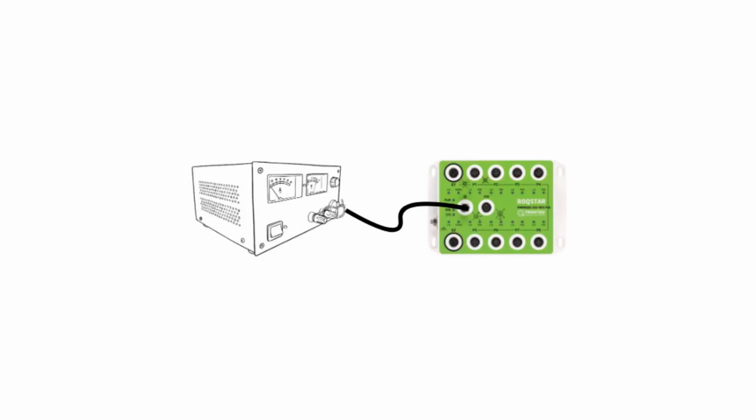First, connect the power supply. The connector pinout is printed on the device. Have a look at the documentation to see the values for voltage and power. Make sure to connect pin V1 to the positive supply pin. It is best to connect both V1 and V2.